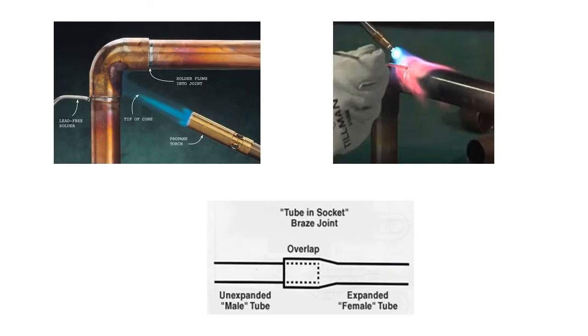Hard-drawn copper tubing is usually joined by soldering or brazing with fittings. Tube in a soft temper can be joined by the same techniques. It is also possible to expand the end of one tube so that it can be joined to another by soldering or brazing without a fitting, a procedure that can be efficient and economical in many installations, and this is known as swaging.